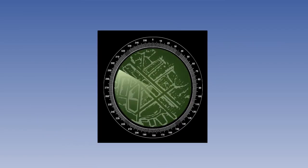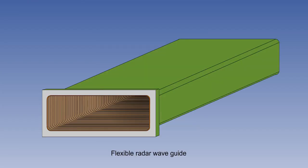Radar beams are directional, and they are narrow. Many ground radars produce an all-round picture, but this is because the beam is rotated. Radar beams operate at ultra-high frequencies, 300 to 3000 MHz, or super-high frequencies, 3 to 30 GHz. Because of the power required for these systems, waveguides are used rather than cables to carry the energy to and from the antenna. These are tubes or boxes, half wavelength in width, along which the energy zigzags. The waveguides may contain air which may be pressurized, or they may contain a vacuum.